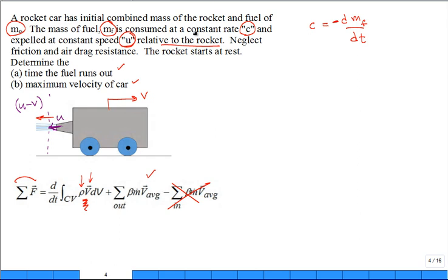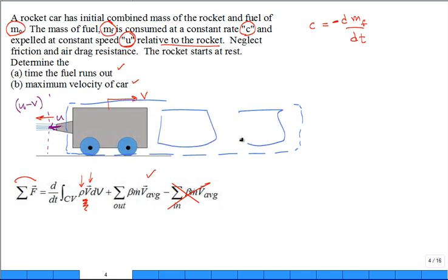So it takes a little bit to think about it. You want a control volume like this. Make it big. Why? Because this cart's going to be moving with time, moving over here, then moving over here. Okay, it's going to be moving within the control volume. And I like to think about a fixed control volume. You can do it a different way. You can have an accelerating control volume, but this way will work in the analysis. And so for that fixed control volume, there's no forces acting on that control volume.